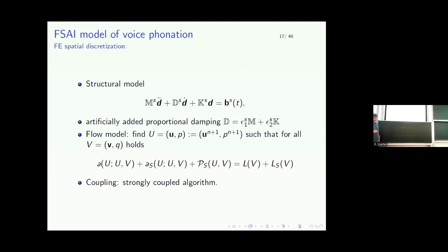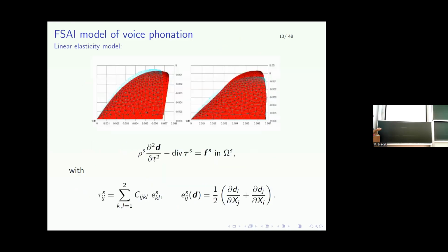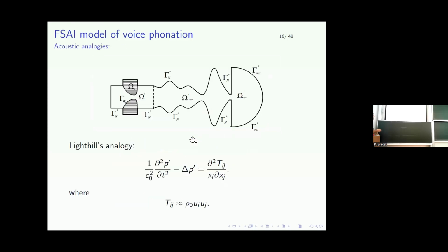Okay. So let me just talk about the finite element discretization. I didn't know how much detail I should include in my presentation, so I only introduce here the application of the finite element method to the structural part. Okay, maybe I can go back. Here we have the second time derivative times density, which after integration is the mass matrix times the second derivative of the displacement, or its representation, and this corresponds to the stiffness matrix.